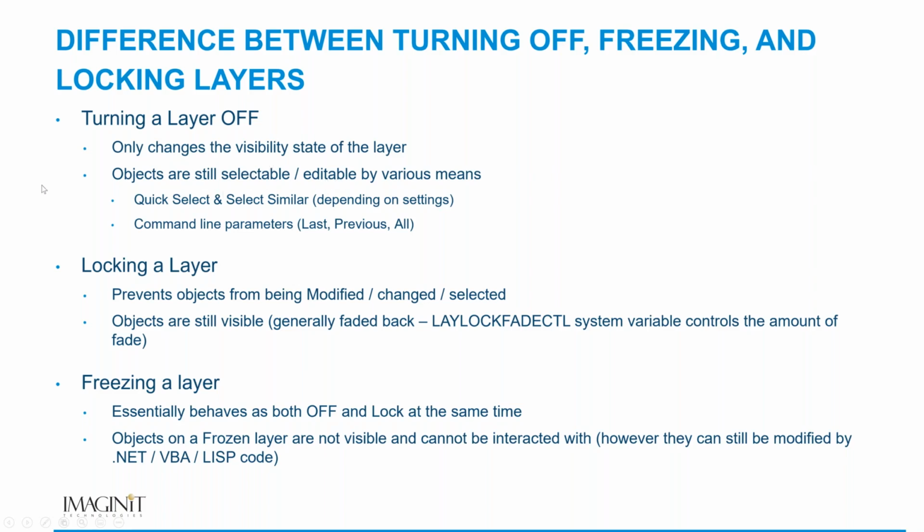It's called Defpoints because it stands for definition points. It's a throwback to the older years where your dimensions actually created 2 little nodes on the Defpoints layer. When you exploded the dimension, you could actually go in and select those.